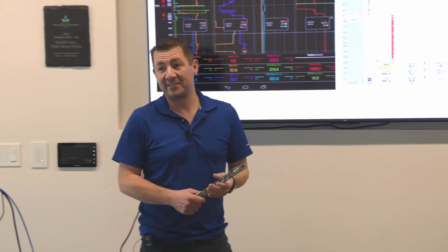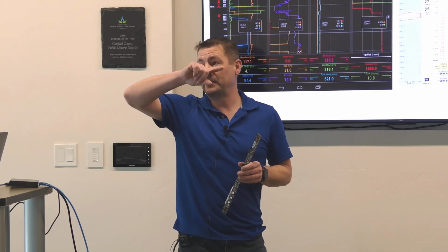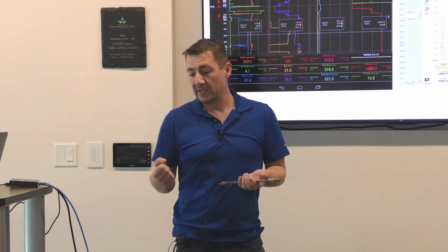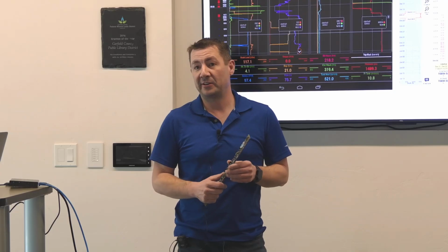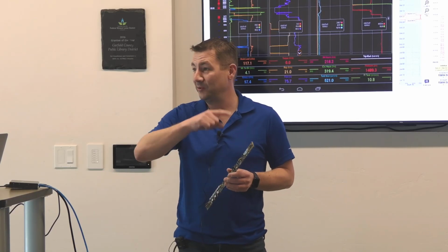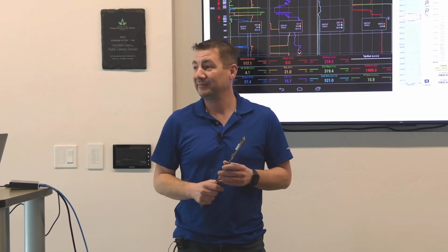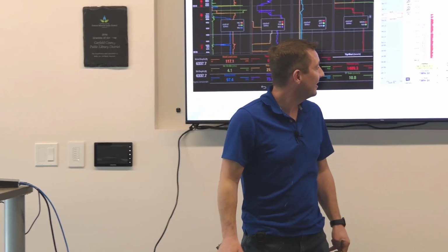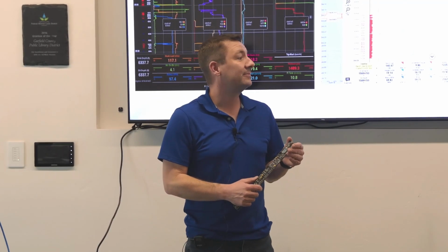Another big thing too is evaporation that comes into play, because when the mud comes back up to the surface, it goes over what we call the shakers to get the hard stuff out. We shake that stuff all out, and the mud engineers have to calculate evaporation as the water comes through the clean out system. Sometimes they'll lose like 15 barrels a day of the fluid that's being circulated through the system. If it's over 100 degrees Celsius coming out of the ground, it's gonna evaporate all over. It's pretty quick.